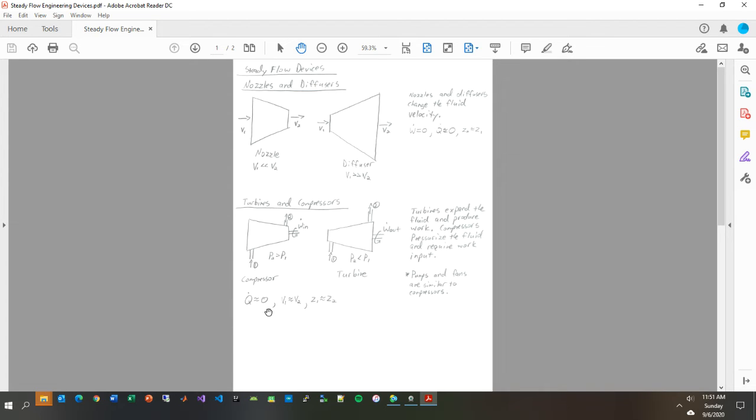Typically, again, we assume that these are adiabatic. Not always, but if you're given information regarding the heat, then you can take this to be not true. If you're not given any information regarding heat escaping or entering the turbine or compressor, you can take it to be adiabatic. I shouldn't leave you hanging like that; I'll probably make a mistake if I don't tell you exactly that the nozzle is adiabatic. I usually throw that keyword in there anyway.